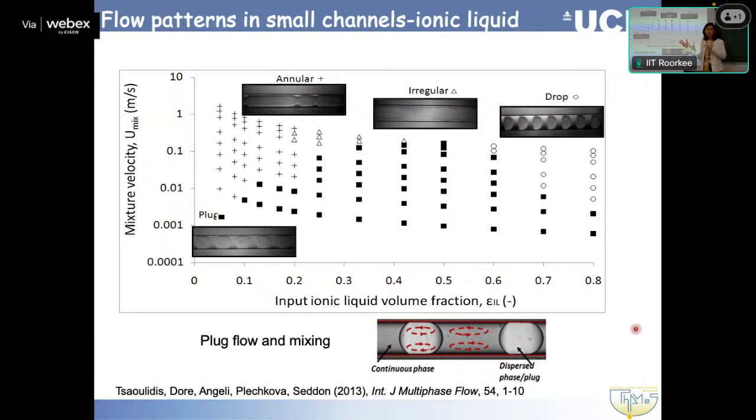So we know we can get them for different conditions when we change the fractions of one phase or the other. And also, what people have seen and we have seen, is that we get these circulations happening inside the phases. So remember, this is all laminar flow. We depend on diffusion. So basically, these circulations break the thickness, because now we don't have to diffuse from here to here, let's say, but we have broken it into smaller regions. The same here and here.